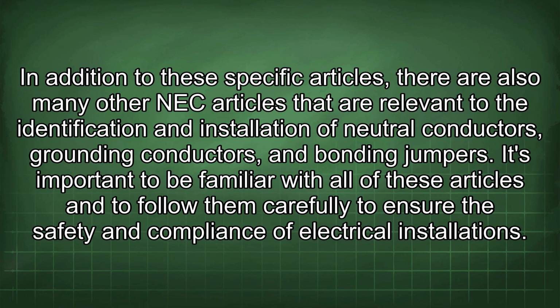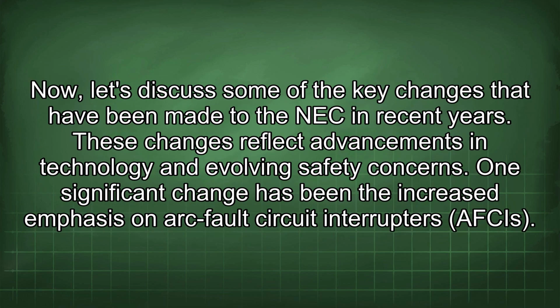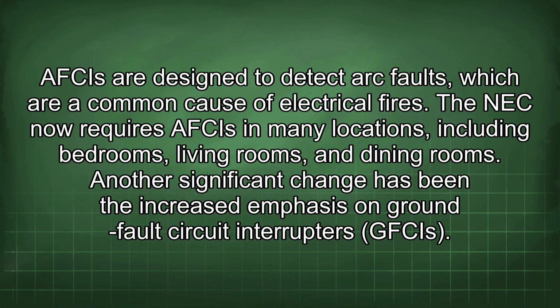Now, let's discuss some of the key changes that have been made to the NEC in recent years. These changes reflect advancements in technology and evolving safety concerns. One significant change has been the increased emphasis on arc fault circuit interrupters, or AFCIs. AFCIs are designed to detect arc faults, which are a common cause of electrical fires. The NEC now requires AFCIs in many locations, including bedrooms, living rooms, and dining rooms.